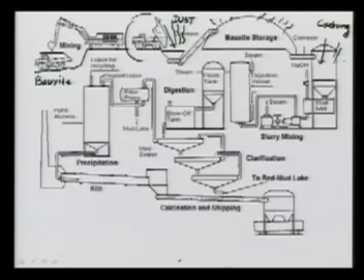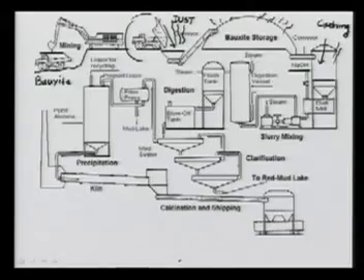Now once we have the bauxite after the ball mill, we mix it with sodium hydroxide. Let's just underline it rather than circling it. Here the sodium hydroxide is added. We'll talk about the use of the sodium hydroxide in a moment, but what you see here is that along with steam, the sodium hydroxide is made, and what you get is a slurry of the bauxite with water and NaOH.